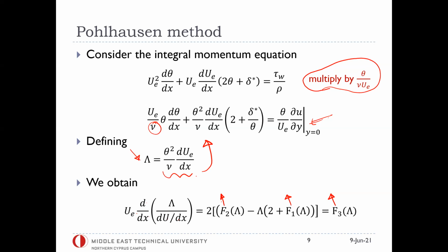So you can see this kind of approach, Pohlhausen's approach, is a little bit more involved than Blasius's approach, but still there's one big limitation. That limitation is that we are still constrained within the domain of laminar boundary layers in the case of Pohlhausen's solution. It can indeed be modified for turbulent boundary layers. But in order to understand what turbulent boundary layers are, we need to learn. We will start from the basics of some turbulence physics.